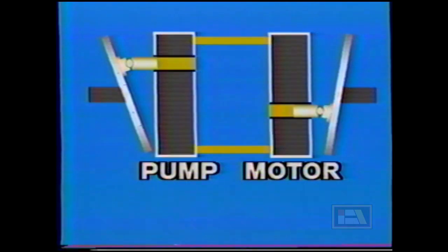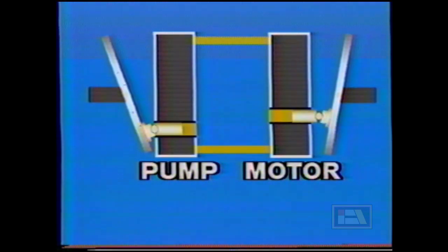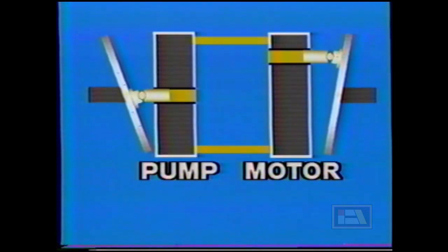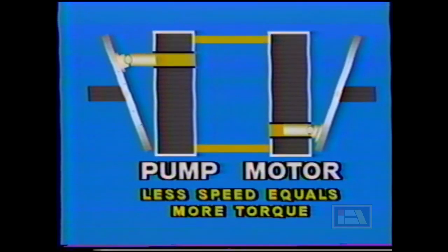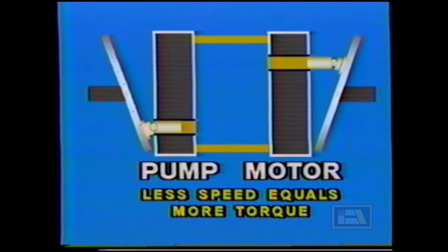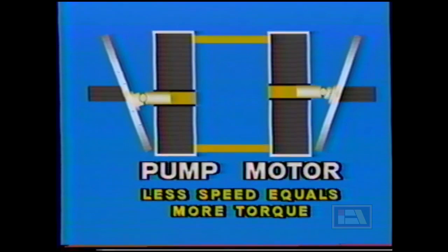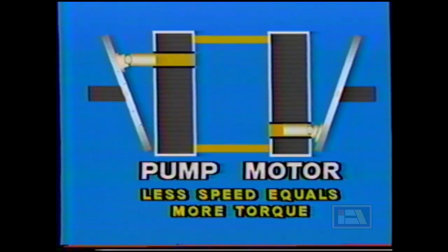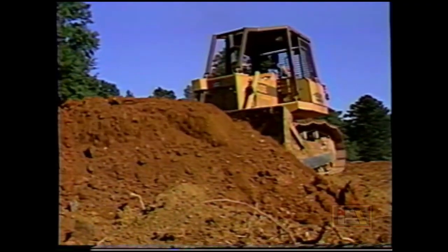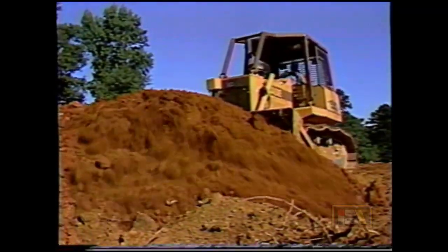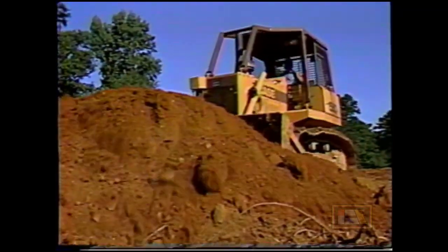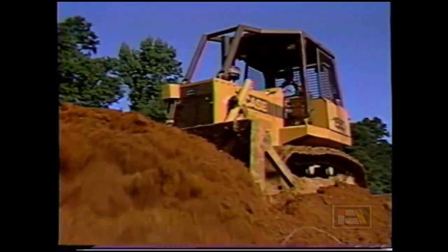When the motor's swash plate is again returned to a greater angle, the speed will decrease. However, the total amount of torque produced by the motor is increased automatically. The higher volume of oil used by the motor develops more load handling capability.